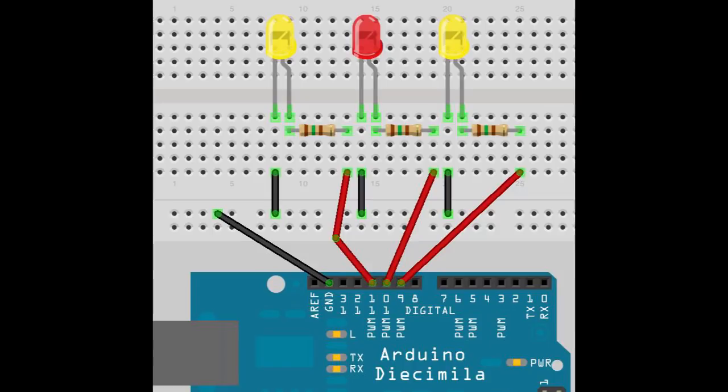We'll begin on the Arduino at the far left side. Notice the gray wire that is connected into the socket that's marked GND. That's the ground pin on the Arduino, and this is the negative side of our circuit. Note that that jumper is connected from the ground on the Arduino to the upper of those lower 2 horizontal lines of sockets. That means that all of that horizontal line of sockets is connected to the ground on